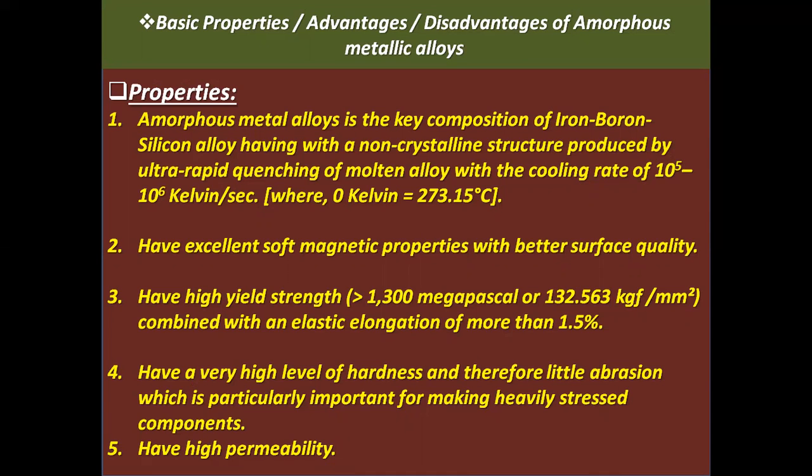Number 2, have excellent soft magnetic properties with better surface quality. Number 3, have high yield strength, that is more than 1300 megapascal or 132.563 kgf per millimeter square, combined with an elastic elongation of more than 1.5%.